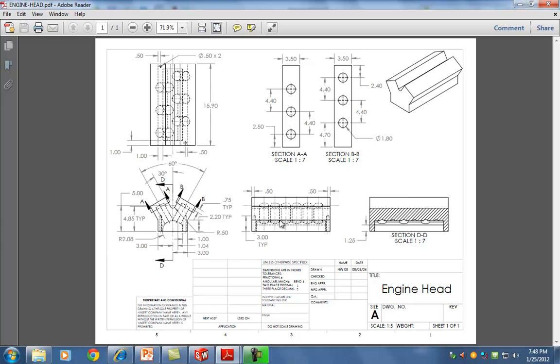So we have the top, front, right as normal. But if I just want to see section AA, which is this slot, I can see over here. So basically I can tell that on this plane, the circles are oriented in this fashion. On this plane, which is this face, the circles are oriented in a different fashion. So you have to do one of them, extrude cut, the other one, extrude cut. Okay, so you cannot do them all at one time because they're two different planes.